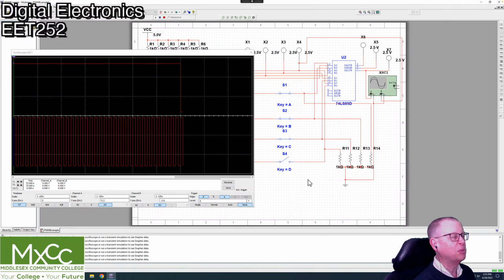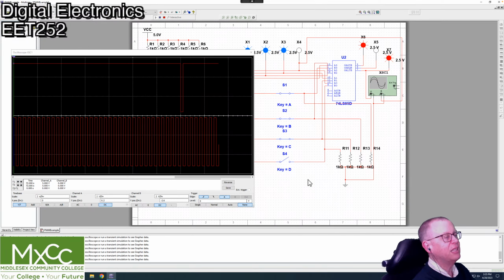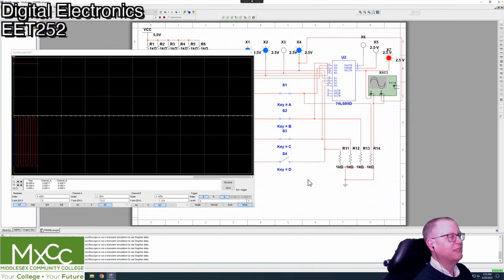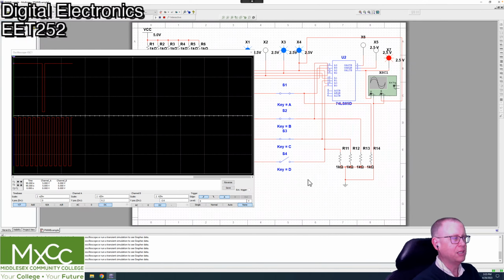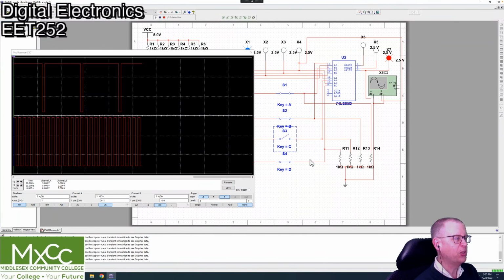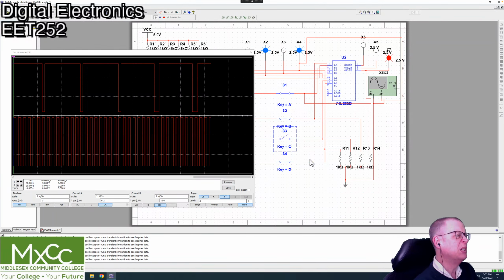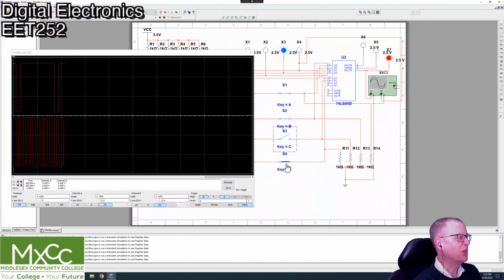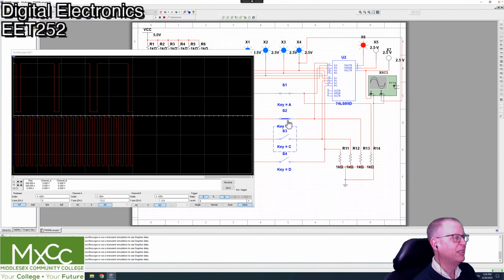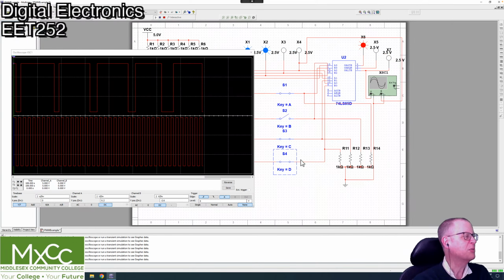And if I change the least significant bit, you'll see that we get a very wide pulse for the duration. Then I can swap those over, and that should give me a slightly wider pulse because I've gone from 1 to 2. If I go to 3, let's wait for it to wrap and get a couple of those on there. Then if I change it to 3, I get a slightly wider pulse again. Then if I change it to 4, oops, that was 5, let's go back to 4. It gets a little bit wider again.